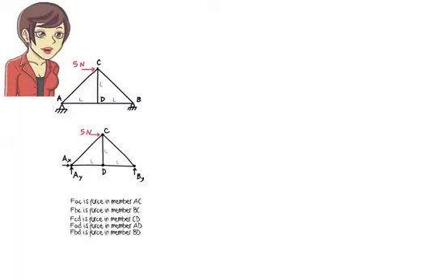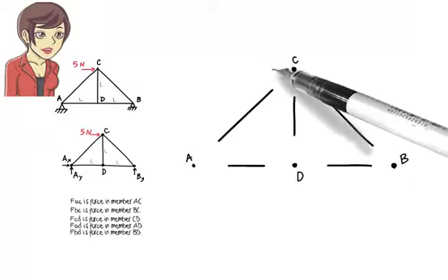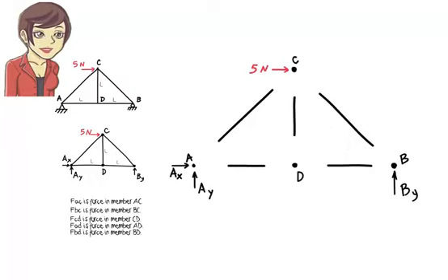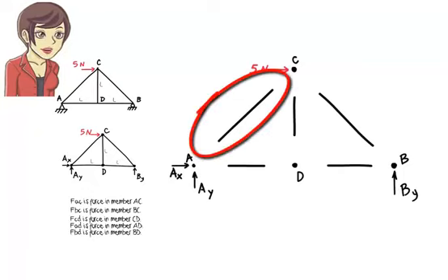Now, let's conceptually separate the members from the joints. That is, we divide the entire structure into 9 segments. There are 5 member segments and 4 joint segments. Let's look at the segment containing member AC. We know the member carries an axial force, but we don't know the magnitude of the force. We also don't know if the force is compressive or tensile.